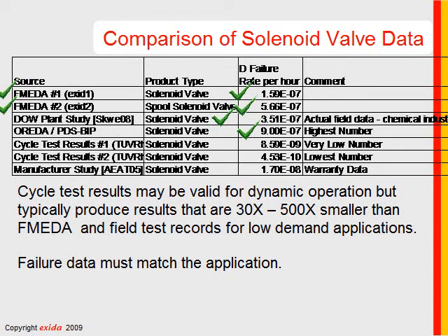If you have relatively low safety culture, if you have relatively poor maintenance capability, and a lot of failures are actually caused by mistakes made by your maintenance and operations people, then those kind of failures would not be included in an FMEDA. Now, I do happen to think it's important that we model those. And so at Exeter, we have a maintenance capability model that treats those very separately.